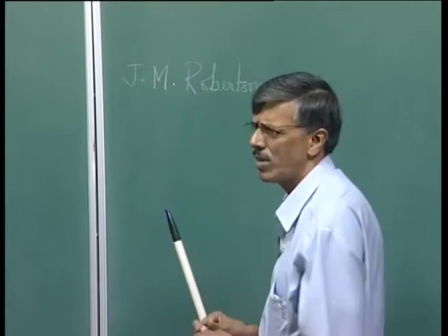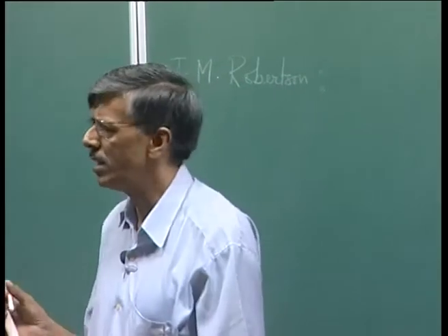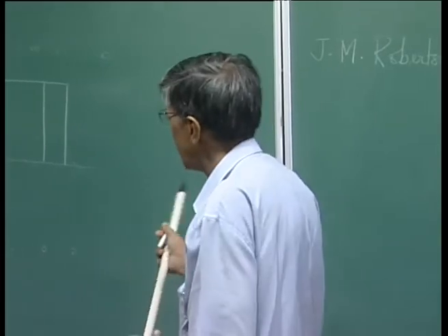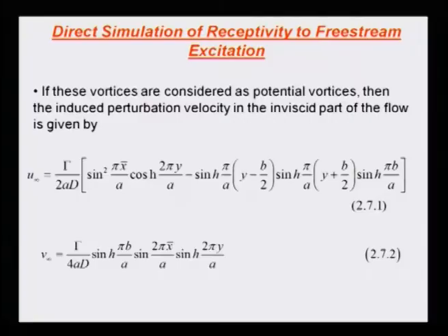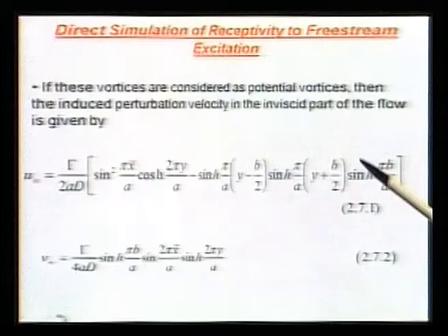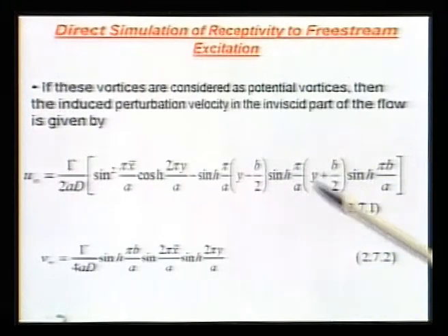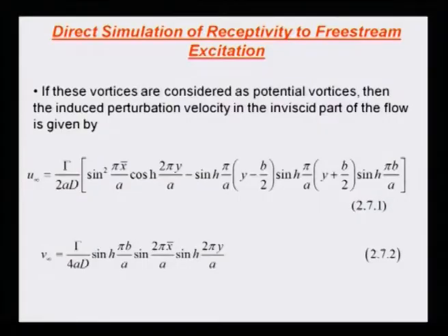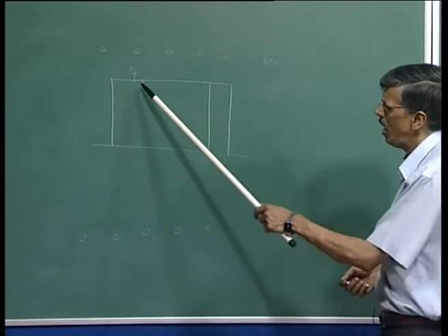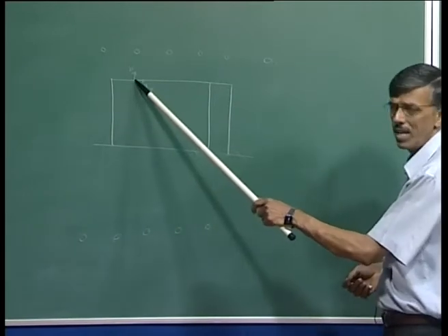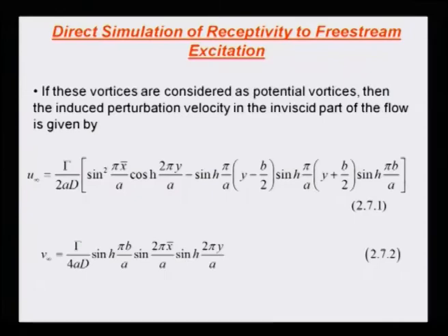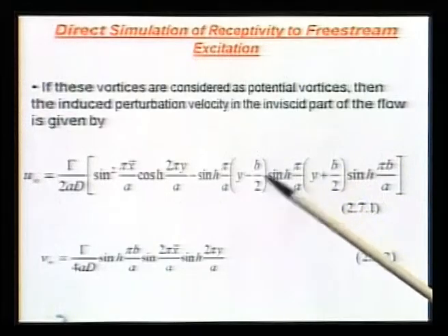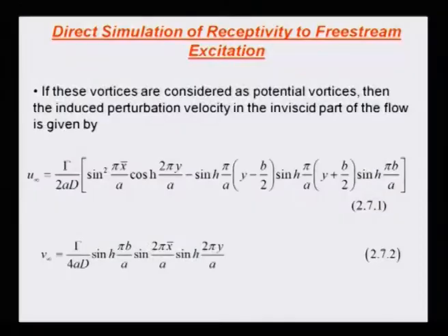The title of the book is, I think, Hydrodynamics. You can take a look at that book where this kind of inviscid vortex expressions are given. So this is basically the u component and v component of velocity as it is applied at some position x and y. Okay, all this sine hyperbolic, cos hyperbolic term comes because we are summing over infinite such arrays.